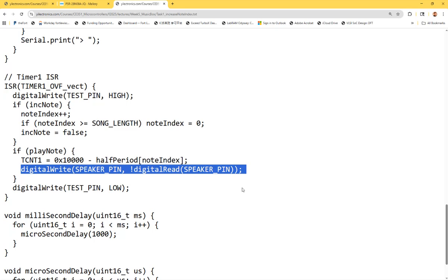Okay, so next time, when the timer is up, we enter the ISR again, because the timer is already up. I want to set up that count into the timer again, right? Which is what this line is doing. Do it and then flip the pin one more time. And just keep doing that.